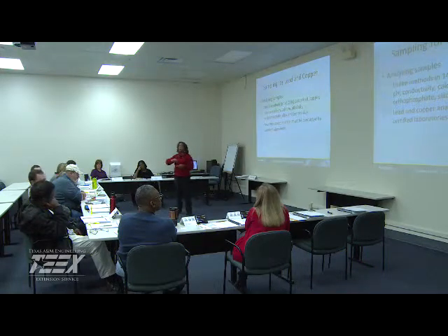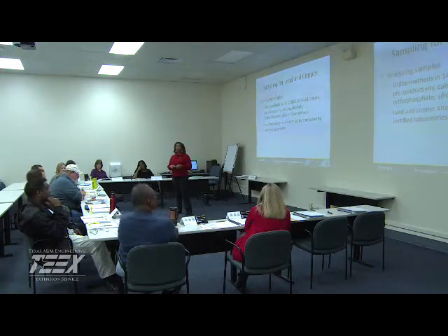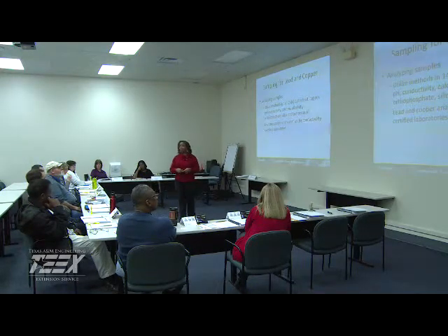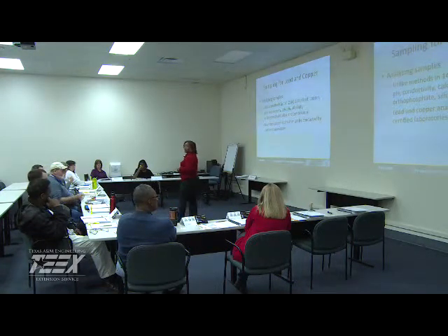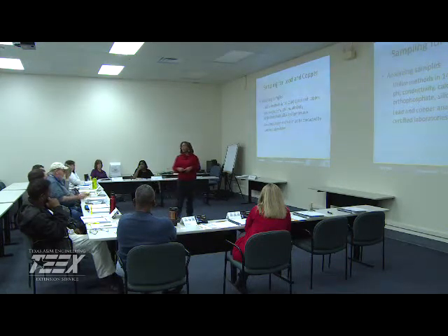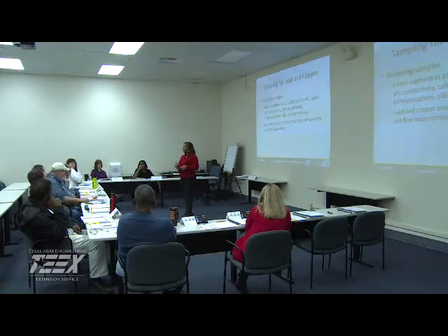Some of those have to be done in the field. pH has a holding time of 15 minutes. You're not going to get it to the lab. Conductivity, I think, is similar. And temperature, of course, you have to do in the field. Now, you have to have a certified thermometer. I'm not sure if they require that for field testing, but I know for our refrigerators, we have to maintain certified thermometers that get NIST certified and all that fun stuff.